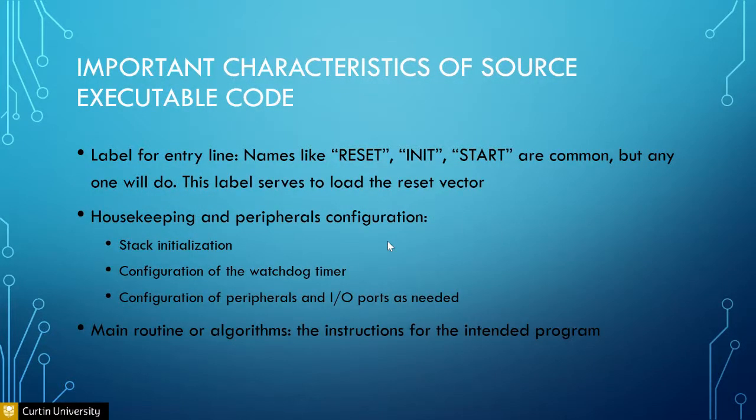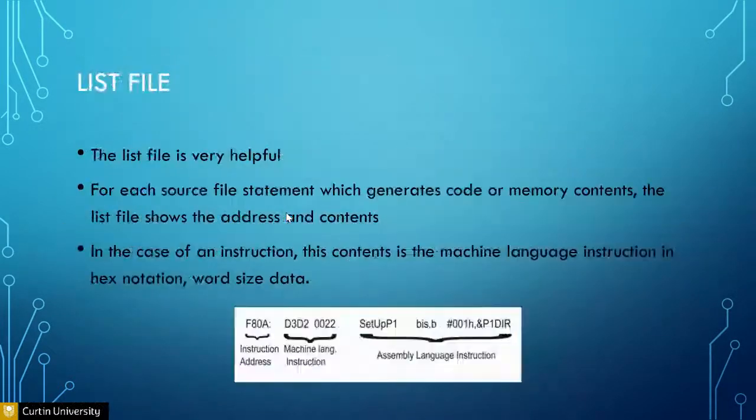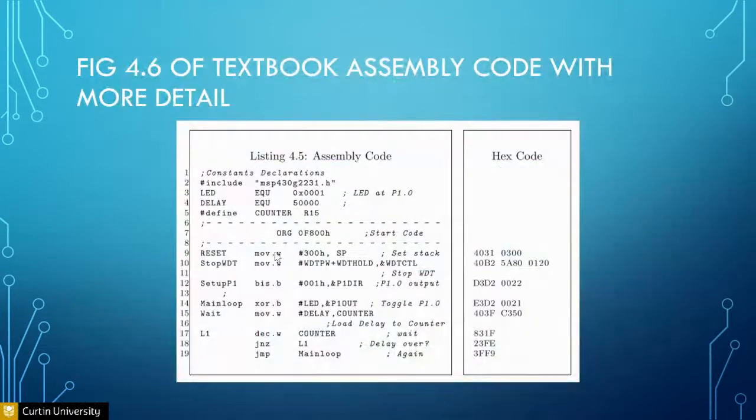And then you have stuff like reset, initial, start. All these are basically a form of labels. So if, let's say, reset is not equal to 0, the program jumps to reset. Okay, so the MSP will jump to the reset address, initialize address, or the start address. All these labels represent an address in the program, just like this. All right, so these are all labels.